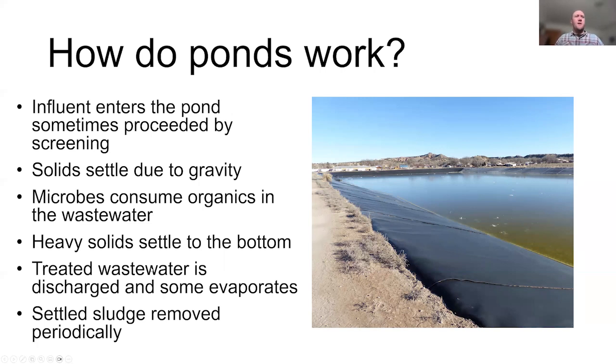And then depending on what kind of lagoon, that treated wastewater is discharged, although a lot of it will evaporate along the way. And then periodically, everything that settles out, that sludge at the bottom, you will have to remove on occasion. That can be variable depending on your community and how big your lagoons are, but maybe something around every 20 years or so. So it's not super frequent.